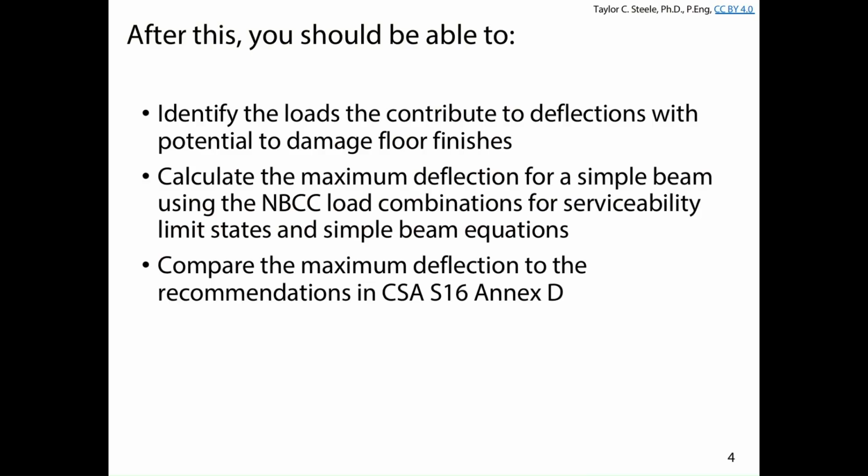You should be able to calculate the maximum deflection for simple beams using the MBCC load combinations for serviceability limit states. So I showed you that in lecture 15, I think, for serviceability of tension members. We'll see how that applies to deflection calculations for steel beams. And you should be able to compare the maximum deflection that you get using those calculations to the maximum limits on deflection, and those are recommendations that are found in Annex D of the steel standard.